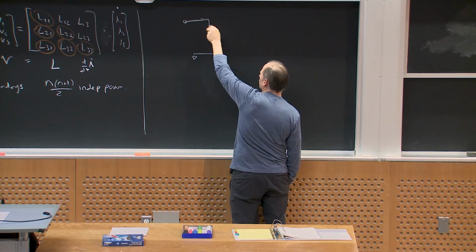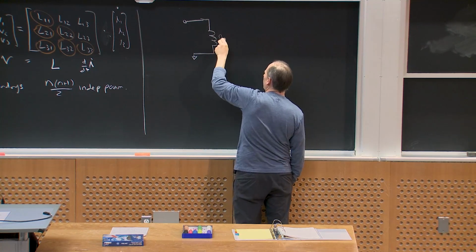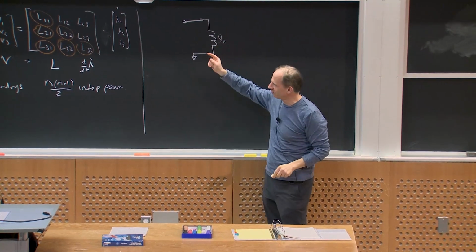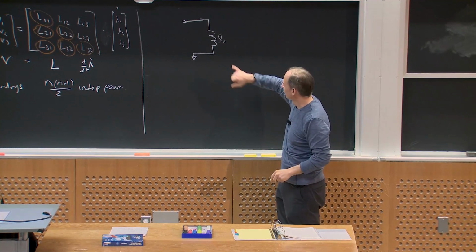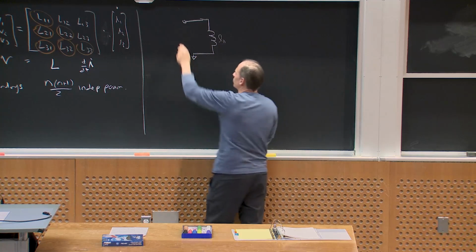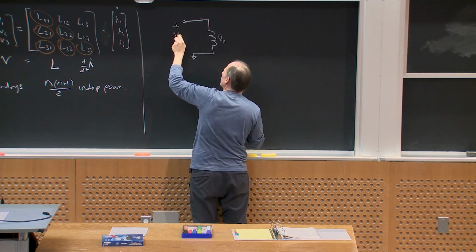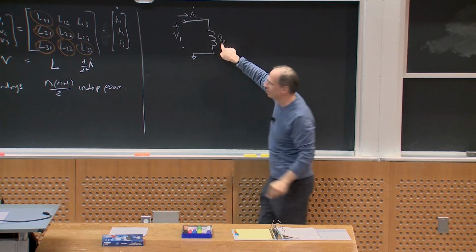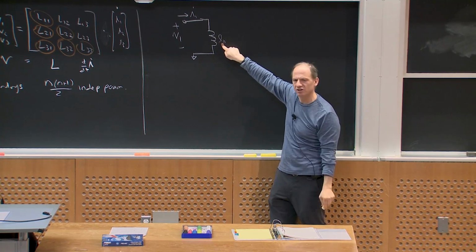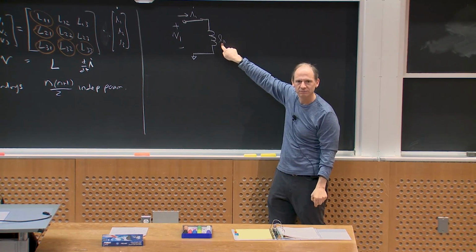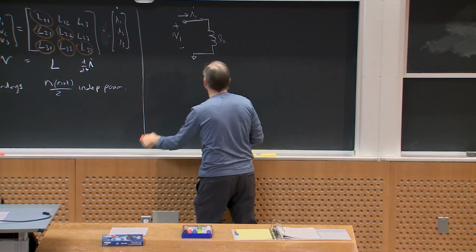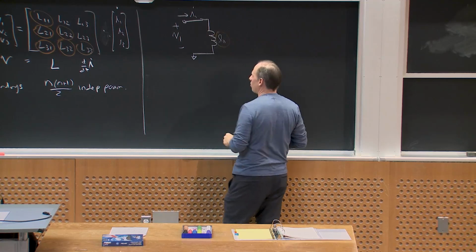This is my inductance L, but maybe I'll call it L11. I'm going to use little L11 to distinguish it from my inductance matrix value, right? If I just had a single device with V1 and I1, I'd need one parameter that I'm going to call little L11, which is just the inductance of that one-turn winding, right? So I have one parameter here that captures what I want.